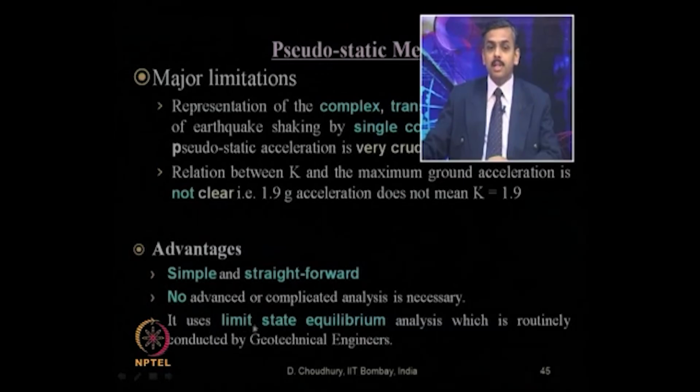It uses the simple limiting state of equilibrium analysis, which is routinely conducted by geotechnical engineers, mostly practitioners, when they want to design any retaining wall in a seismically active region to consider the seismic earth pressure on the retaining structures.